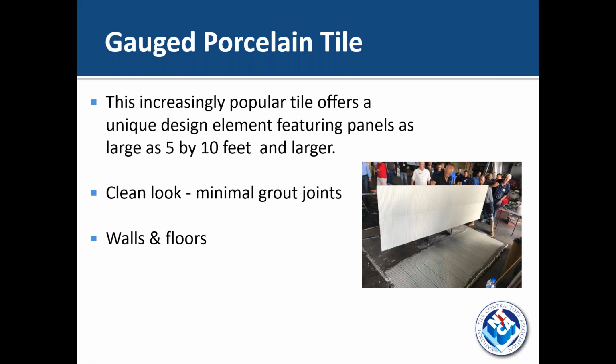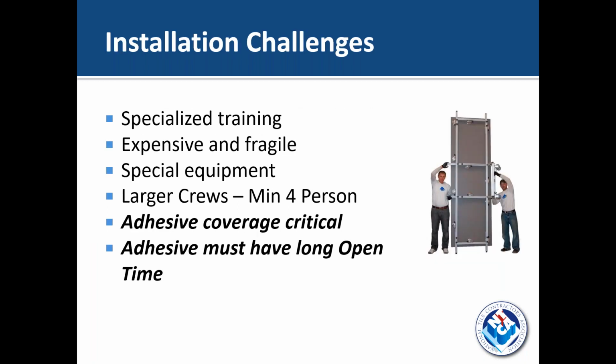A little bit about gauged porcelain tile. This is another relatively new product. You can see on the slide just how large these panels can be. They offer a really unique, clean look with minimal grout joints. They can be as large as 5 to 10 feet and are used on walls and floors. It's a great look, as I said, and gaining in popularity, but there are some challenges in installing this material. It's a much different installation than traditional tile, just because these panels are so large and so thin.